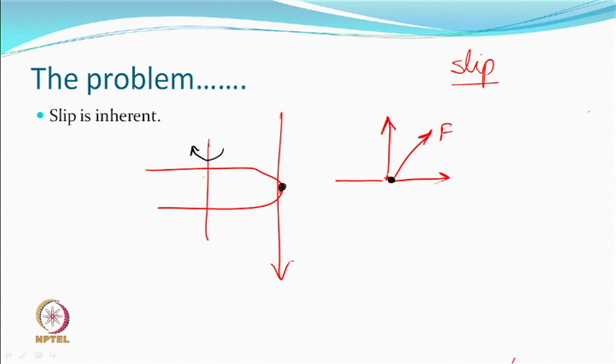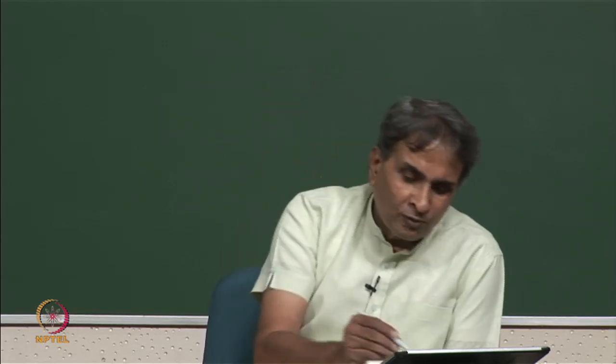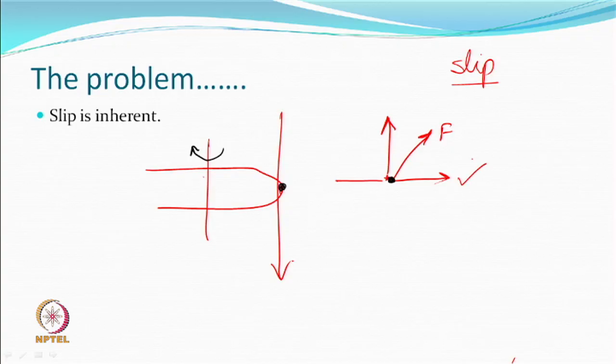So, the frictional force, because of the movement of the yarn, will be upwards, acting opposite the motion. The disc is rotating in one direction, opposite to that there will be another frictional force. So, there are two forces, one this and one this, at that point acting on the yarn.